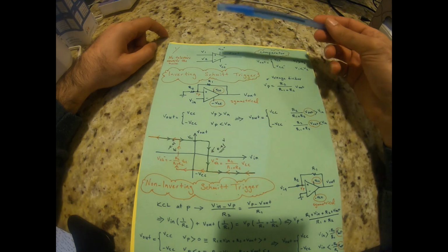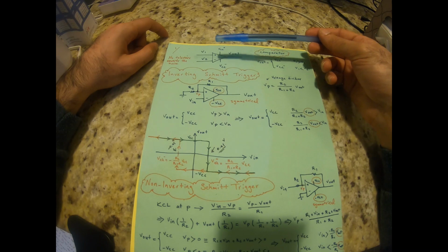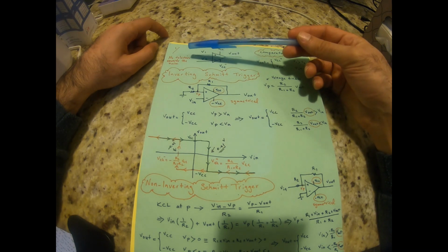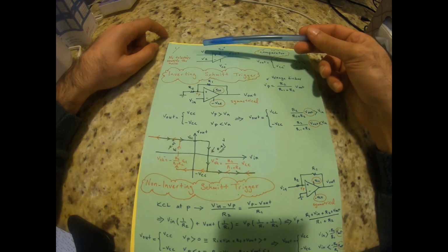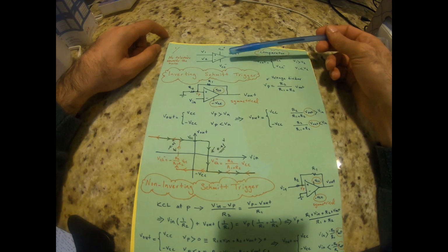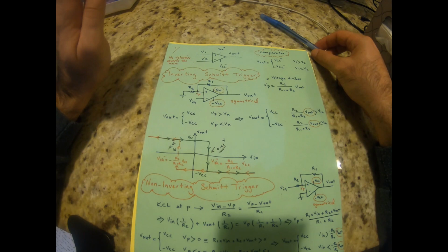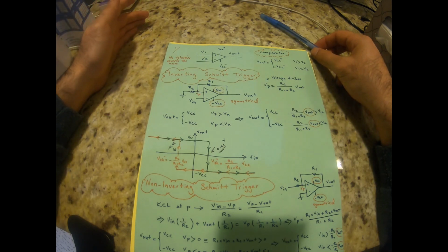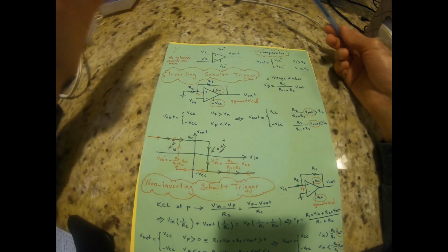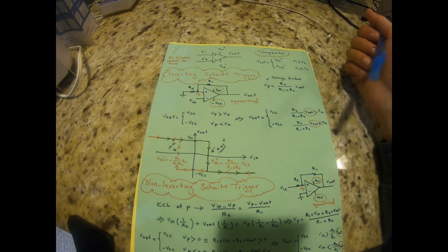As mentioned earlier, one of the problems with this comparator is that it's very sensitive to noise and it doesn't have any tolerance. So if V1 gets slightly bigger than V2 or slightly smaller than V2, V out changes. In practice, we would like to have some tolerance and threshold towards noise. So the solution to that is the inverting Schmitt trigger or non-inverting Schmitt trigger.